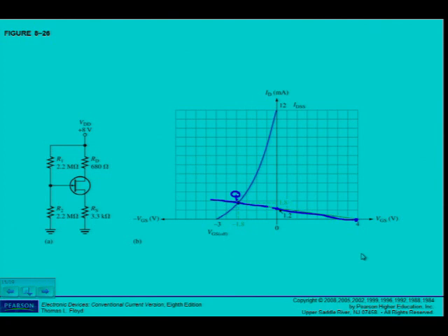And then what you're going to do further, because I only look at this, I don't look at your calculations, I want to see on this graph that you know what you're doing. Then you will draw a broken line to show me what is the parameters for the Q point for the values of ID and VGS. And I can see here, in this case, ID is equal to 1,8 milliamps and VGS is minus 1,8 volts.